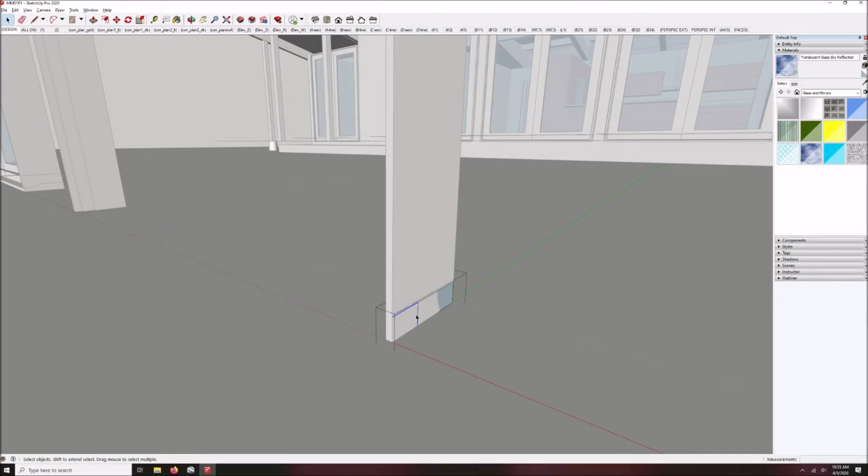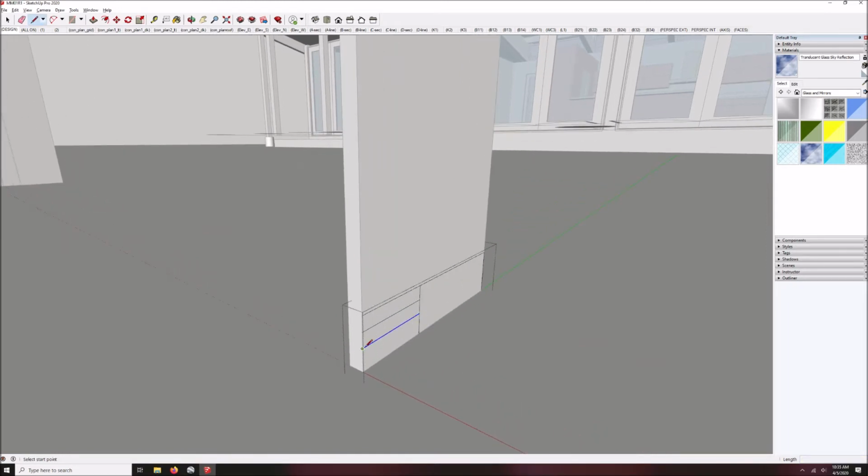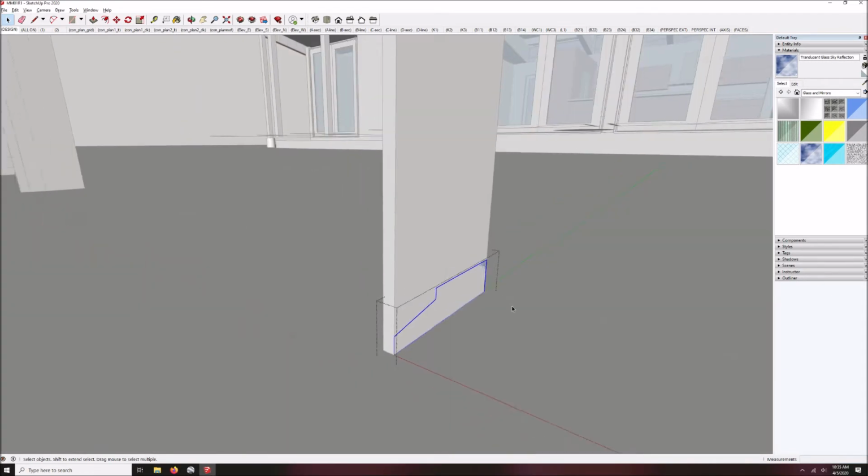Then I'm going to do this front sloping part of the door sill that sheds the water to the outside. I'm going to M Control to make a copy. I'll go down 1/2 inch, and then make another copy down 1/2 inch. The sill is actually sloped between those 2 points, so I use those as a reference to do the actual line I want. Now I can erase the bits I don't need. And that is my door sill profile.